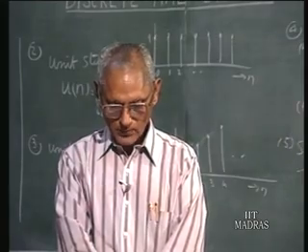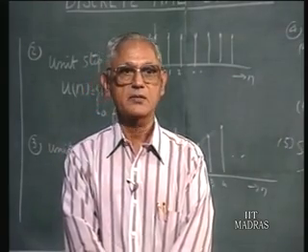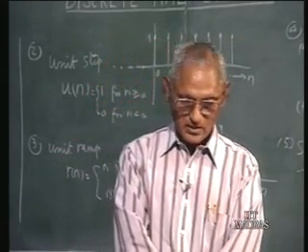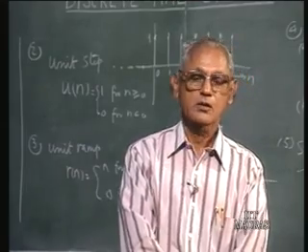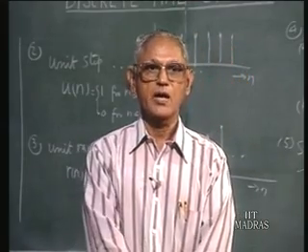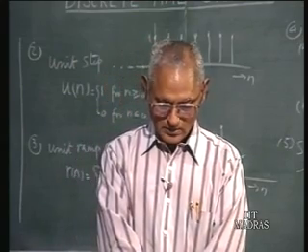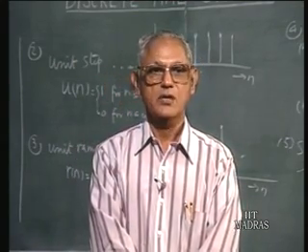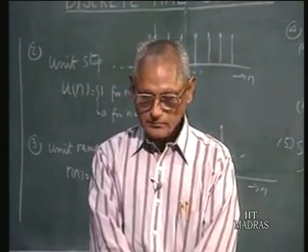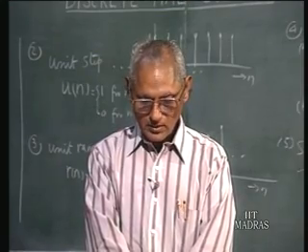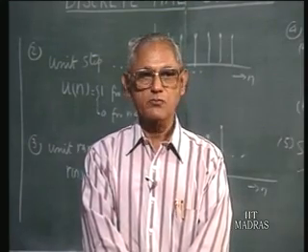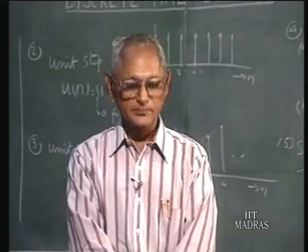We also discussed the difference between a digital signal and a discrete time signal. A digital signal is also a discrete time signal, but the amplitudes, the values of the signal, are also quantized, allowed to take only discrete, well-defined values, not any value in between. Then we talked about a discrete time system, which is one that processes discrete time signals.